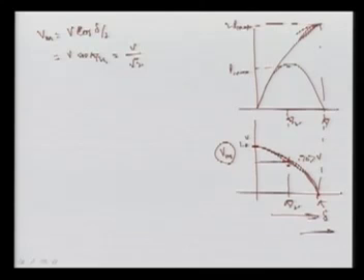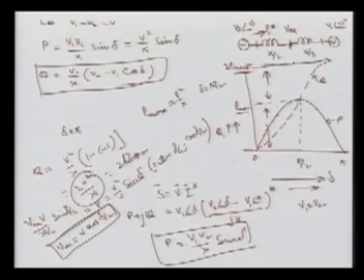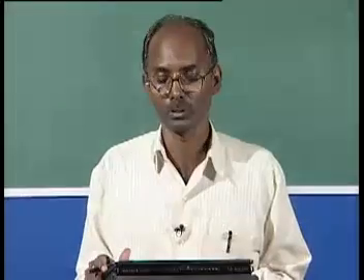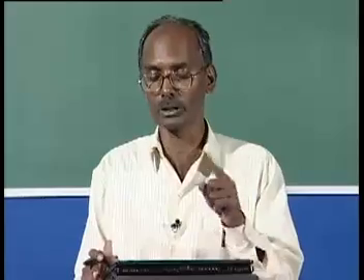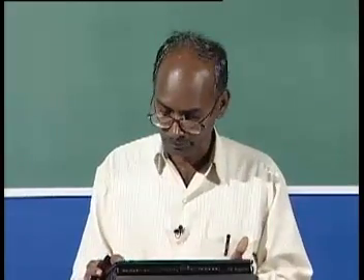Now what I am going to do, let us say we are maintaining that voltage to V by any device here. Means I want to put some device here and that is your FACTS controller. It may be your SVC or STATCOM. With that we can maintain this voltage by varying this XC or injecting some reactive power to the system. Means we are maintaining the Vm voltage at V, and let us see what improvement we are going to achieve.